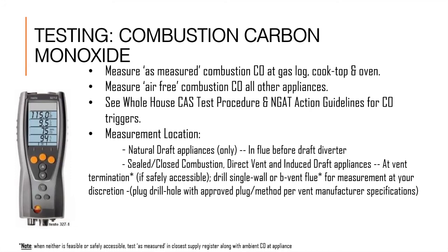This slide introduces us to the importance of understanding the difference between air-free measurements versus as measured. The easiest way to remember is that air-free measurements are assuming that there is no ambient air mixed into the sample of air being analyzed. Lastly, understanding the location of where the sample, the gas, is taken depends on which type of appliance.